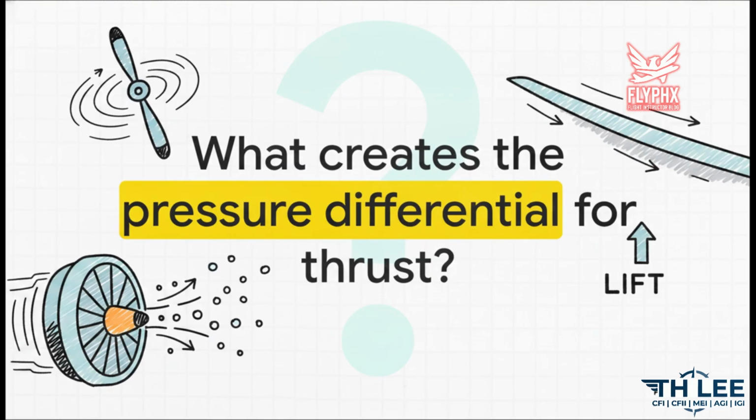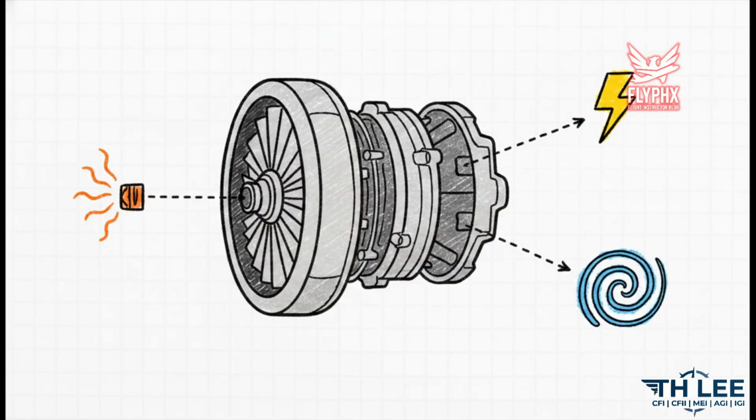So, let's put this all together. We've built the monocoque fuselage, we've attached the strong cantilever wings, and we've secured the empennage to the back. But what incredible feat of engineering actually creates the massive thrust required to overcome the crushing force of drag and initiate the sheer miracle of flight? Well, that brings us right to the power plant. Securely housed within a streamlined air-ducted cowling or nacelle, which is specifically designed to force cooling air directly over the hot engine cylinders, is your engine.